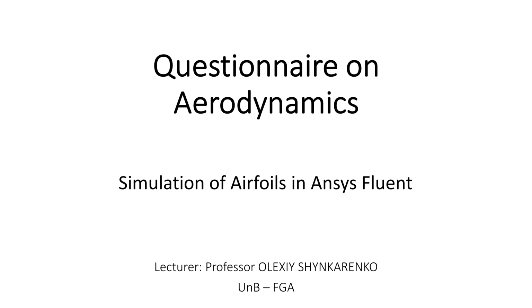Like which kind of condition do you mean? Just the error, just to talk about that. I took angles of 0.2, 1.7, 3.2, 4.5, 5.9, just like the table in the article. And the error I found after the changes on CN, in percentage, is 5.47 for 0.2. Then 11.22, 17.35, 21.66. Yeah, okay, it can be bigger when you approach stall condition.